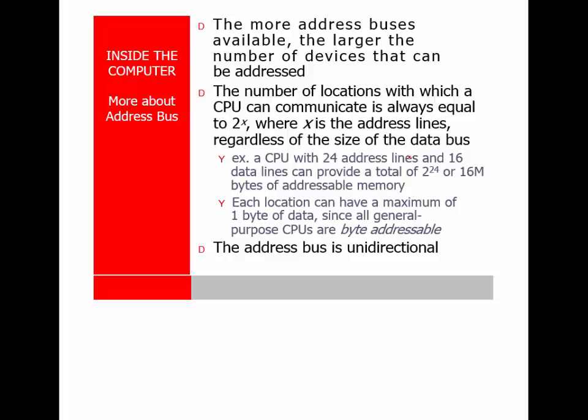The address bus is unidirectional. The only one that writes to the address bus is the CPU, the microprocessor or microcontroller. That's the only one. The data bus, everybody can write to, and that's why you have to decode, but only one at a time.